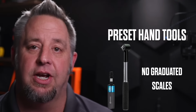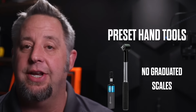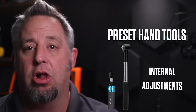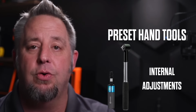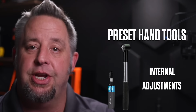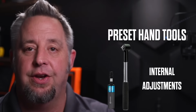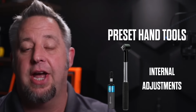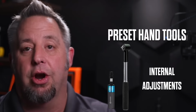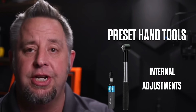You can't look at it and know where it is set. All of the internal adjustments for the torque value are done inside of the tool. That tool is then validated on a torque analyzer to make sure that the torque we are getting is what the tool is producing.